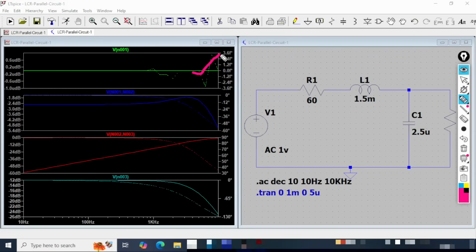Now let me bring my marker pen here. This is the original voltage, that is this one, and the AC response as we see across the resistor, right? That means the frequency variation is on the x-axis, right? We are varying the frequency from 10 Hz to 10 kilohertz, okay? And in decades. So this is one decade, second decade, and like that it goes on. You have a logarithmic graph at your end. You can check these decades. So these are prominently displayed there.